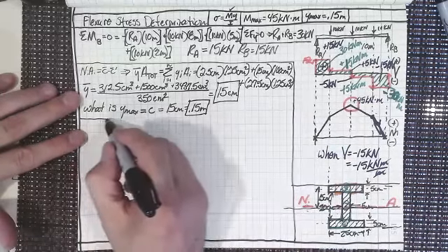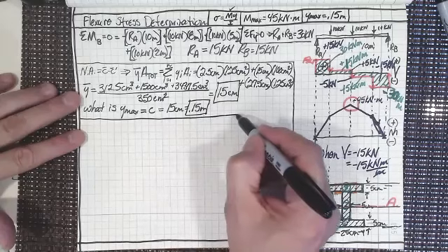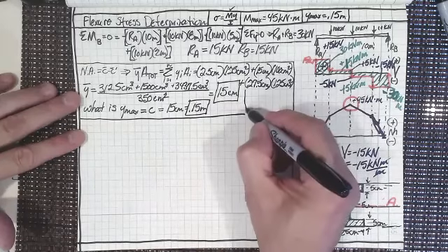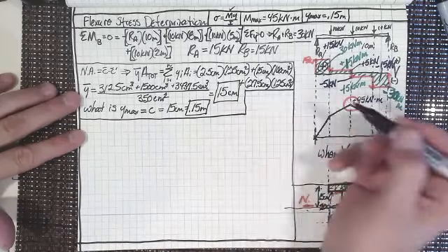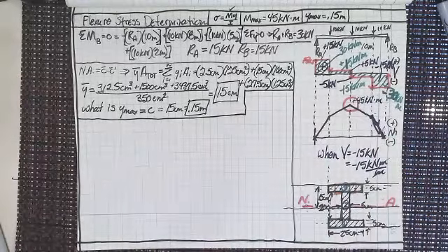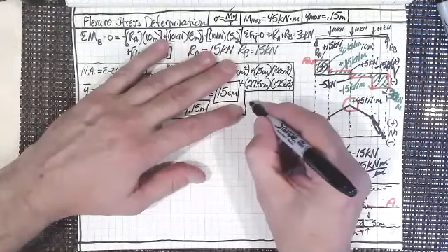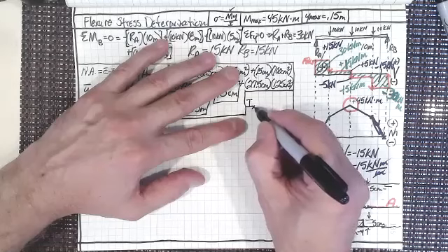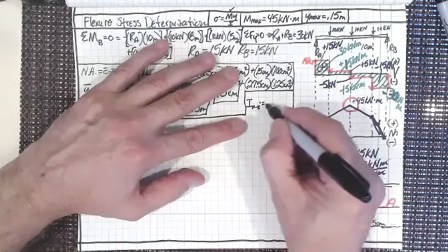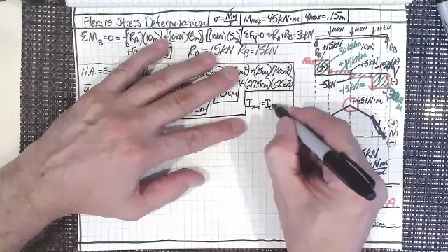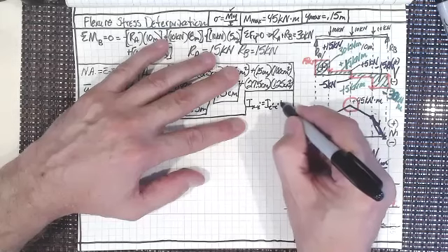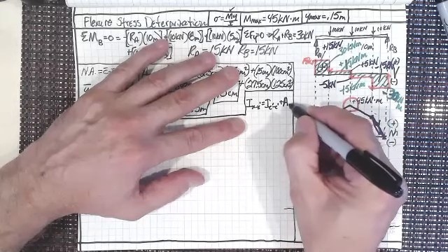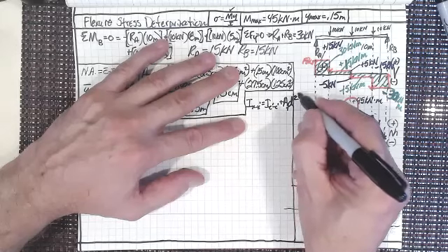So the last thing that we've got to find out now is the moment of inertia of that cross section, and that's going to require the parallel axis theorem. So I of x prime equals I of c prime plus the total cross-sectional area times d squared.